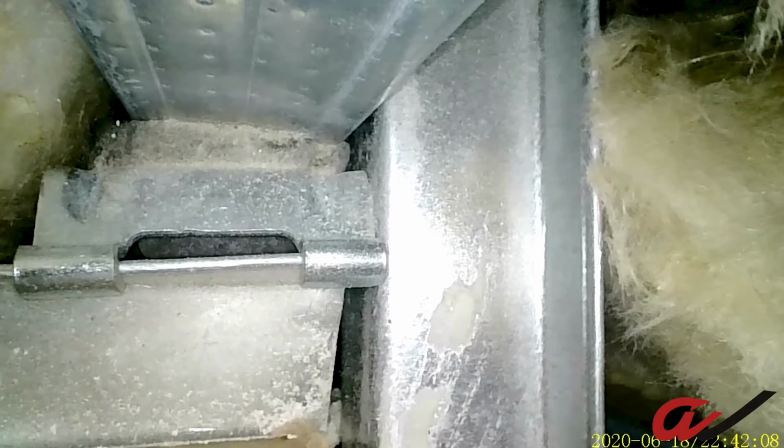And then if you look at corner details with the inspection camera, and some of these images are included, you look at the corners and there's places where there's big gaps at the corner. It's supposed to meet in the corner. The other thing is there was supposed to be a caulked perimeter with these isolators, and the isolators are never supposed to touch other metal. You basically have a spring attached to a channel that's floating the drywall, and it's never supposed to touch other stuff. Well, it's funny, inside the wall with the inspection camera, you find that that's exactly what's going on.